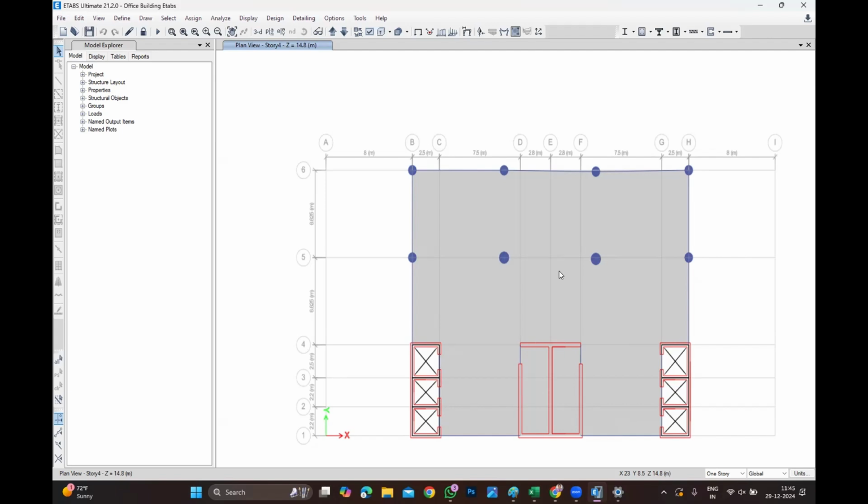See, there are 4 kinds of systems. One is the bearing wall system, which they're not going to use. A bearing wall system typically has no column and no beam. It's a wall and the slab is going to rest on top of it. If you demolish the wall, the slab will fail. This is the bearing wall system, typically used in our home country.